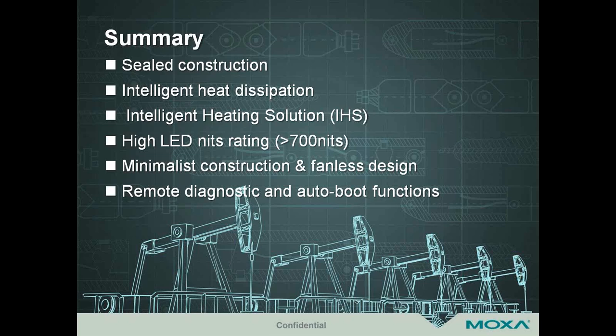And the second part of IHS is that the heat will be focused on the LCD screen, the panel itself. A lot of times, as I mentioned earlier, the computing unit should turn on with no problem at -40 degrees Celsius. It's extremely cold. The screen won't work at that point. So with that said, we need to have a different heating attention placed on the actual LCD display versus the computing unit. An intelligent heating solution will do that as well. It will heat the crystals, not necessarily the computing unit at all times.